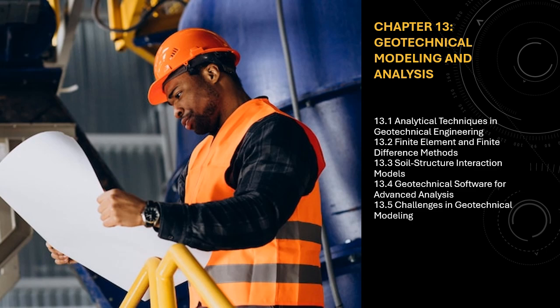Simplified models, e.g., Winkler or beam models, are useful for initial designs or when computational resources are limited. Advanced models, e.g., FEM or BEM, are necessary for more complex or critical systems, where the interaction between the structure and the soil significantly affects the performance and safety of the system.